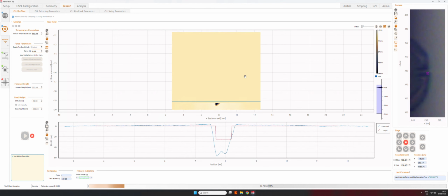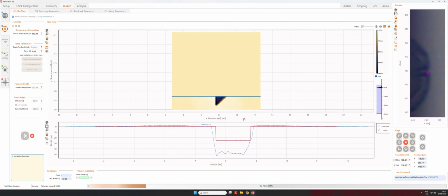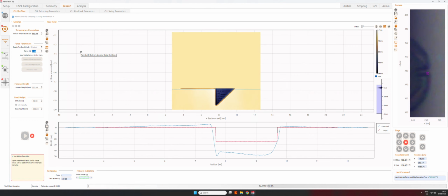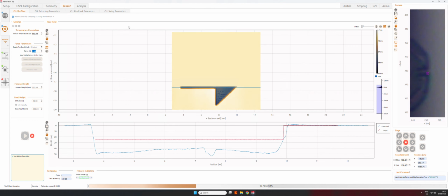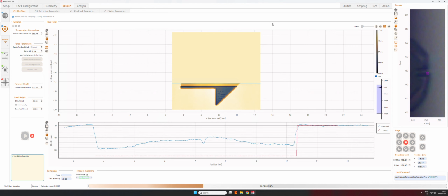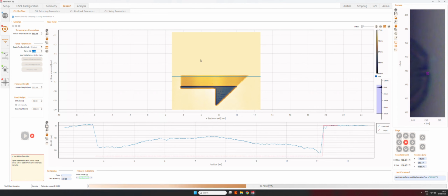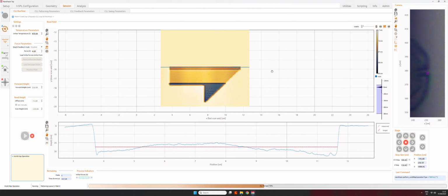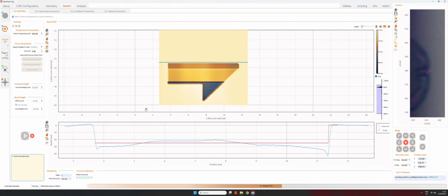So yeah, we see our nice pattern. Probably the force is already too high. We can put 3.5 maybe. Okay, yeah. 3.5, 4. Let's say 4. Let's use a constant force of 4 for the temperature map. And you see we have a depth of 25.